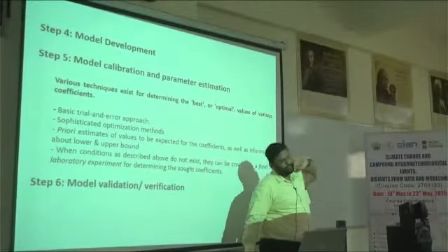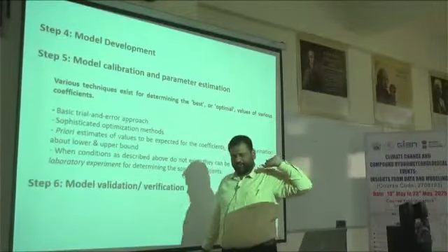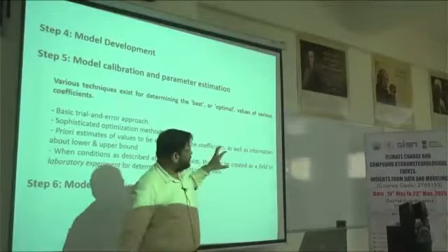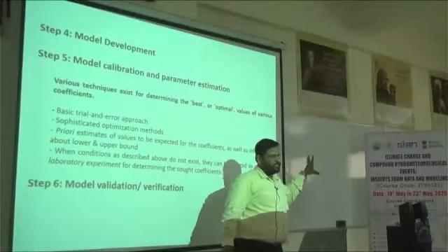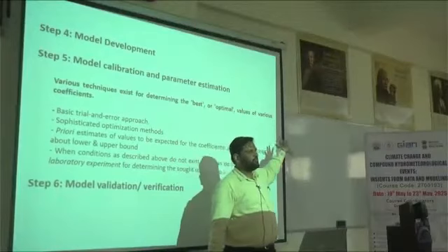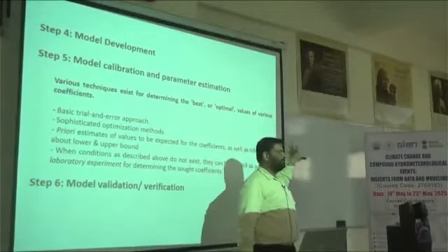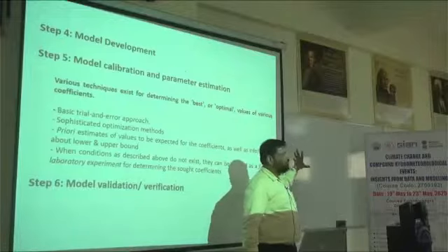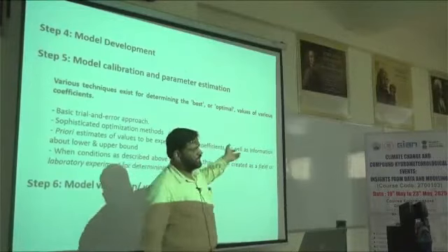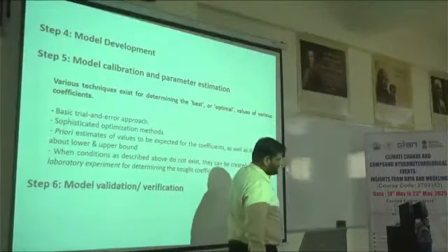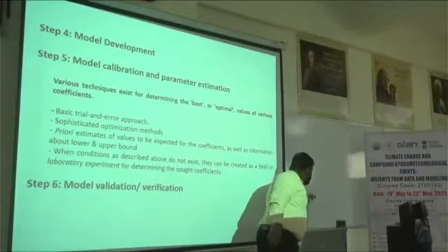In this case we don't bother about the actual hydrology or actual processes, we just focus on matching the observed and simulated. Most of the time the students do over-calibration. So they get very good results during the calibration period, but once they go for the validation period, they do not get good statistics.